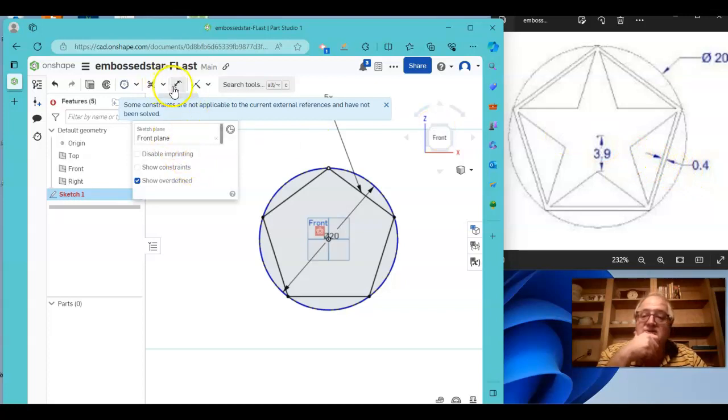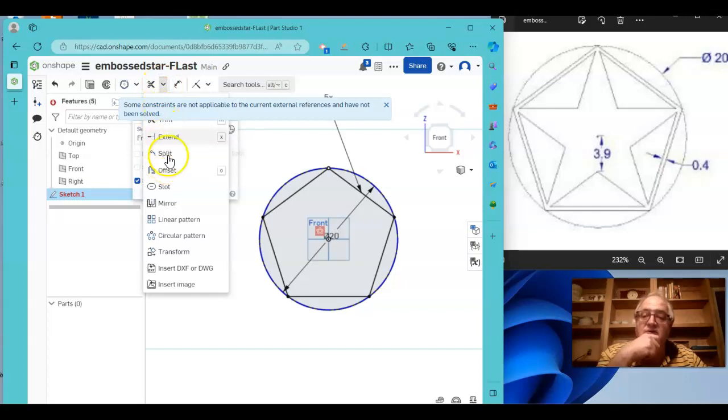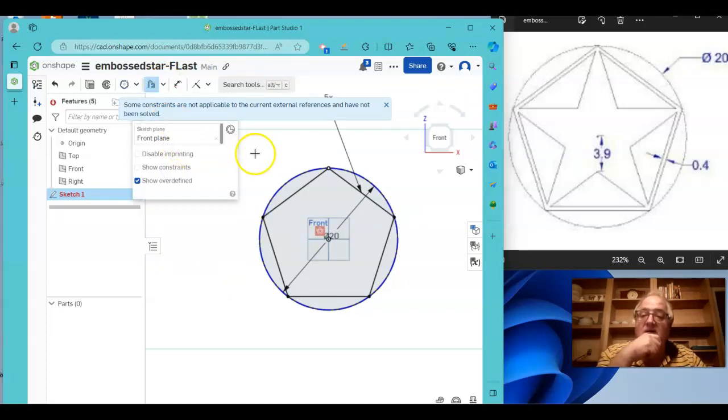So let's try the offset tool. At this point, our offset tool is going to be right here. Click on your arrow, go to the offset tool, and click the offset. Now, one thing is it won't pick up on the whole shape. So we have to left click, and notice the arrow is wanting to offset it that way. So we'll also have to left click on the arrow to switch the direction. Now, it's also given me a 0.25 offset dimension.